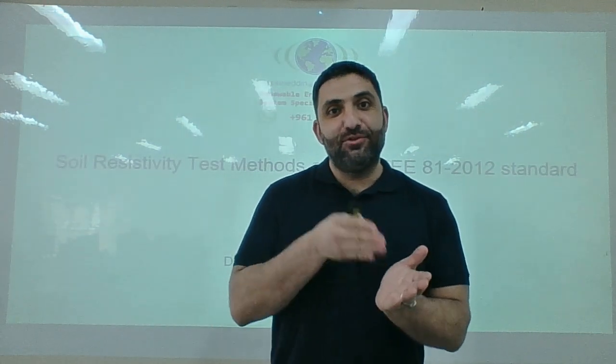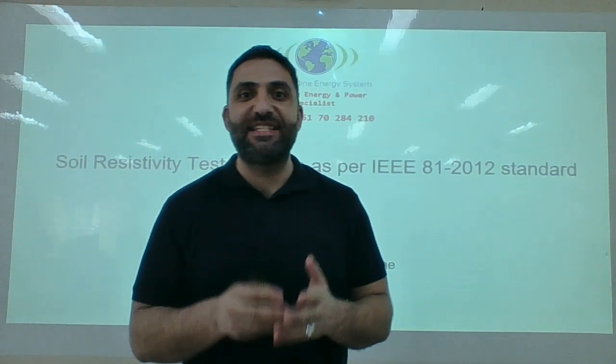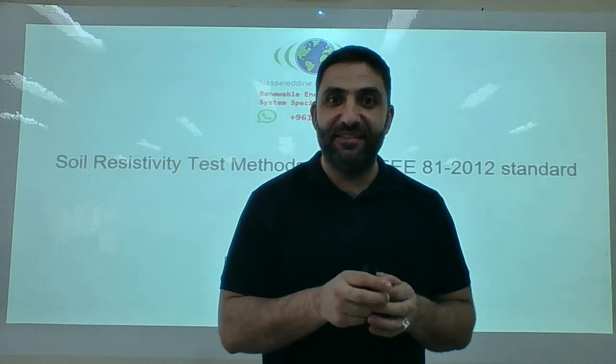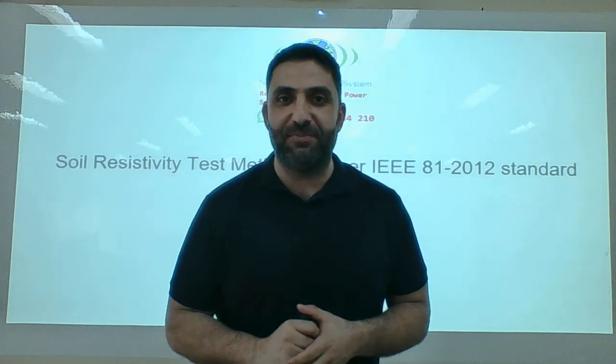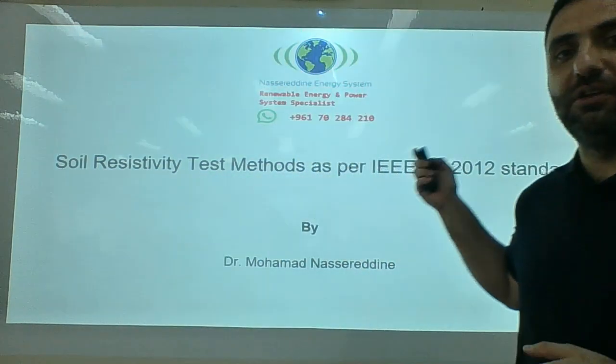So, during today's lecture, we are going to focus on soil resistivity. Soil resistivity is very important when it comes to your earth grid resistance. Also, soil resistivity has a direct impact on your allowable safety limit, which also has a direct impact on the setting of your relays for protection purposes. Let's start lecture number 1 on soil resistivity.